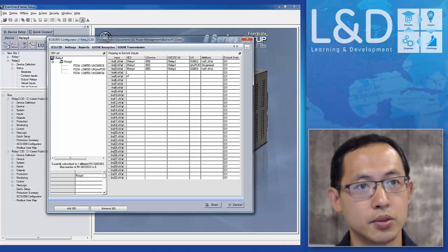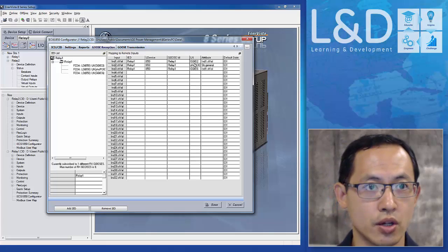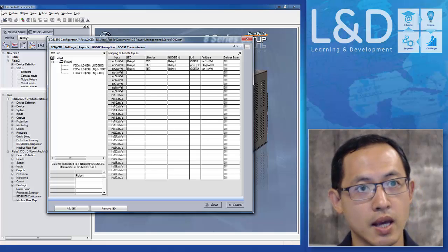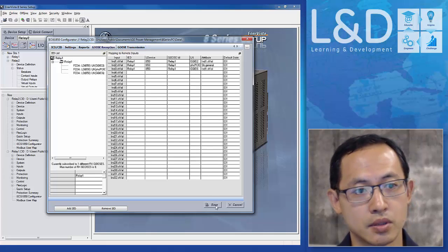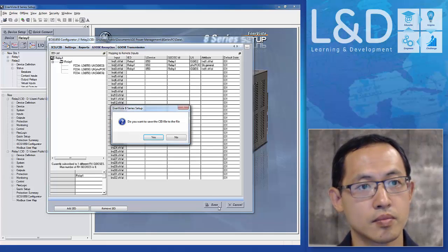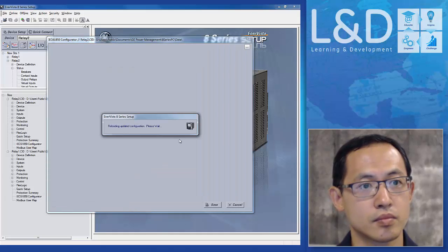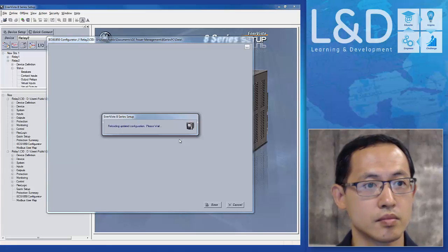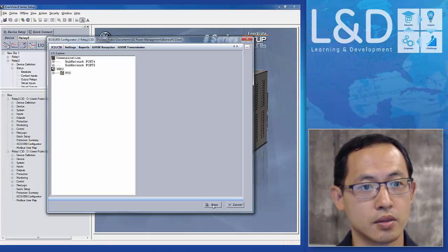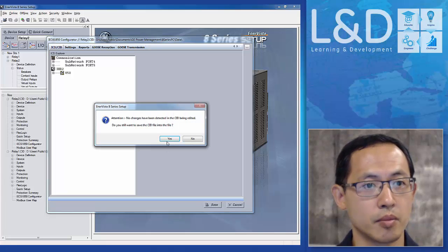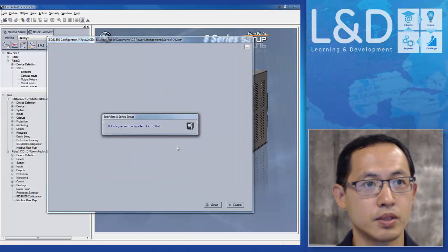So this relay 2 will receive 3 GOOSE messages from relay 1: GGIO2, that's a contact input, the phase IOC pickup, and the contact output. Okay, so now I'm going to configure the relay 1 reception.